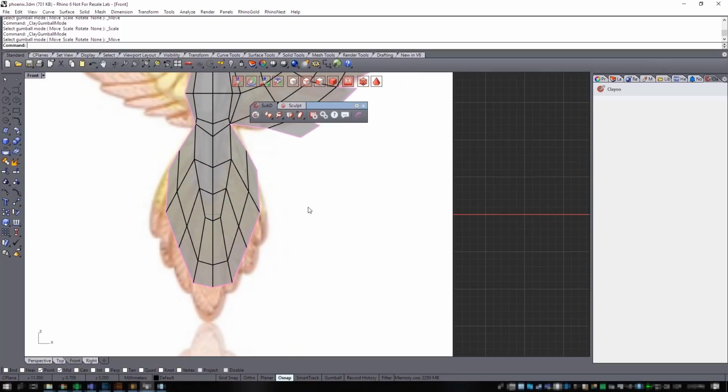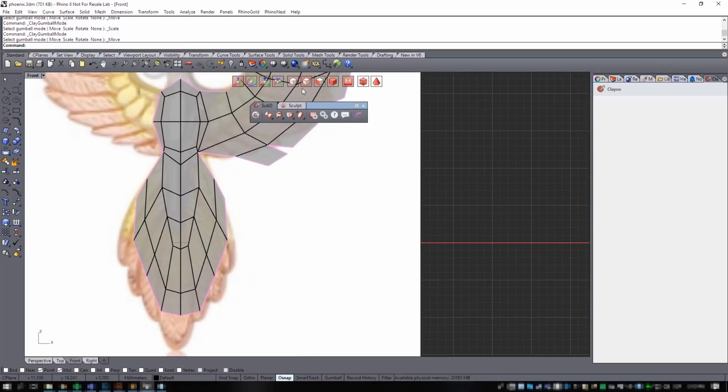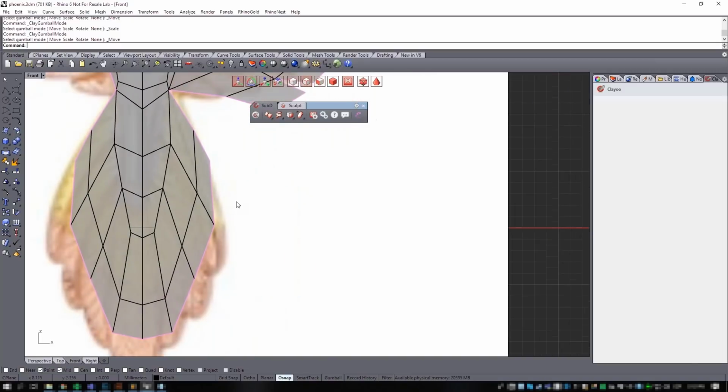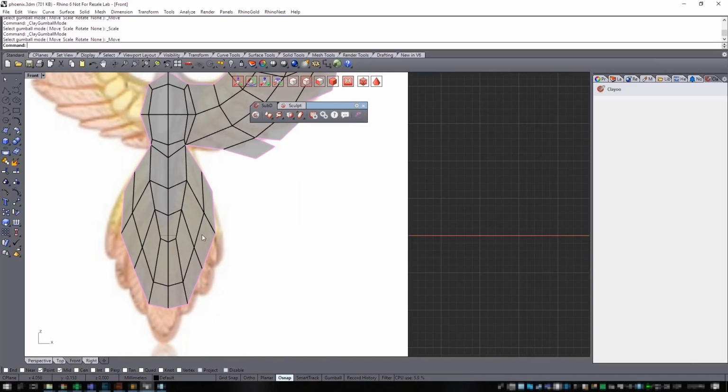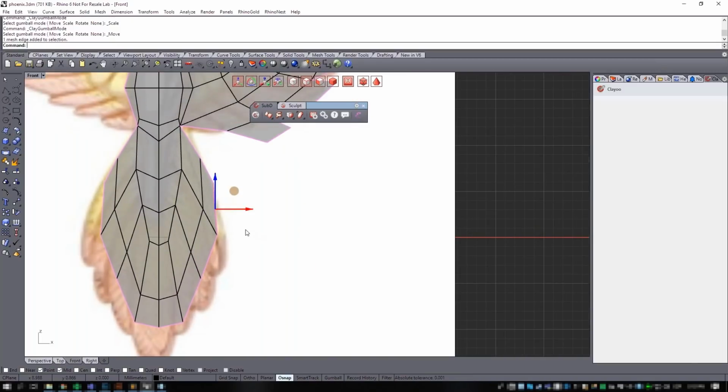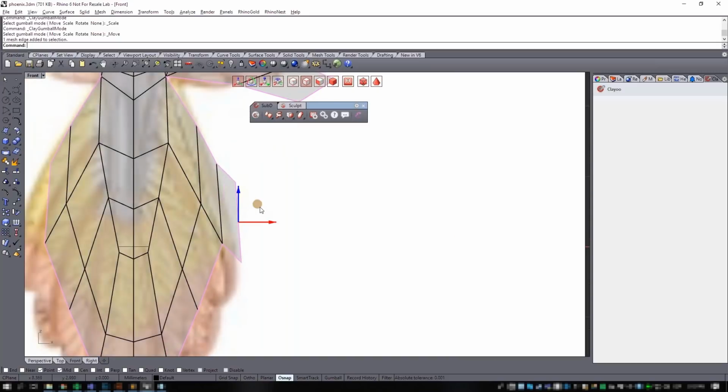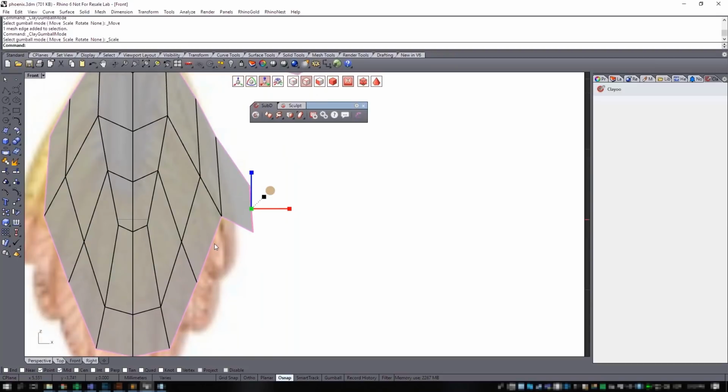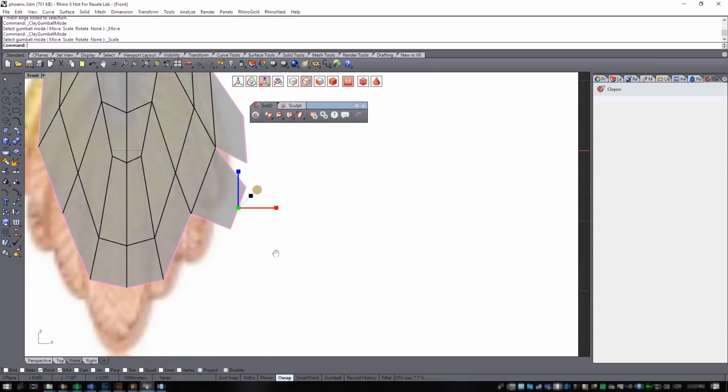And right now to end it, we're gonna do exactly the same that we've done in here. So the last part, right now I will just do it in one half of my model. So selecting this edge, holding Alt and extruding a little bit. Maybe I can scale that also. Same in here, next edge, W, holding Alt a little bit and R to scale slightly.